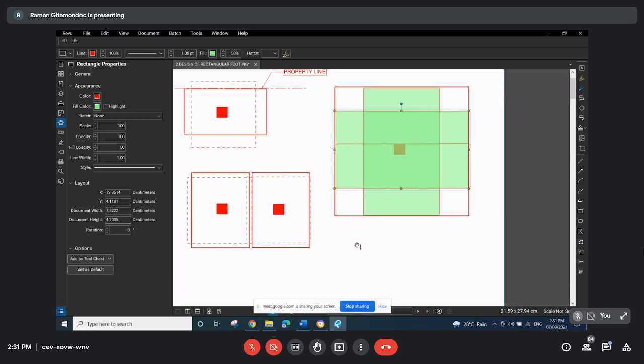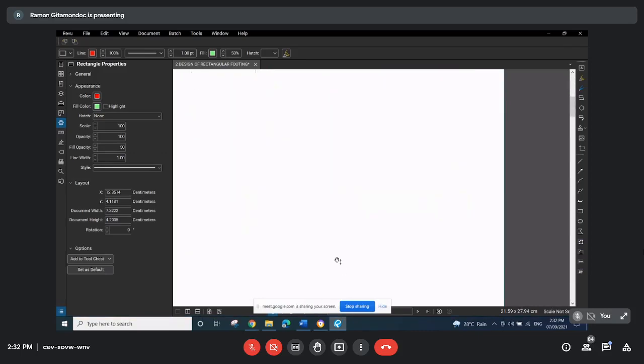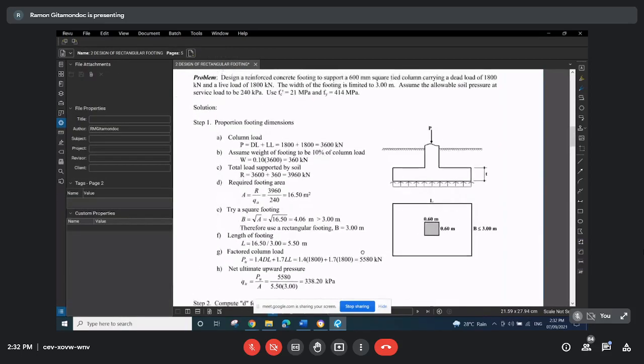There is also a situation where your footing is large and not so thick. So it will behave more as a flexible footing rather than a rigid footing. Our calculation is based on the assumption of a rigid foundation. That is why we didn't consider the footing-soil interaction anymore. Okay.